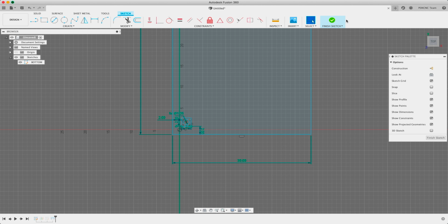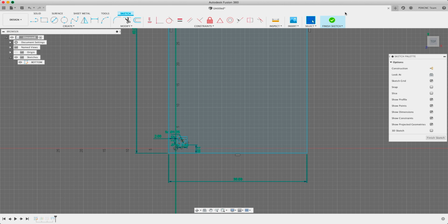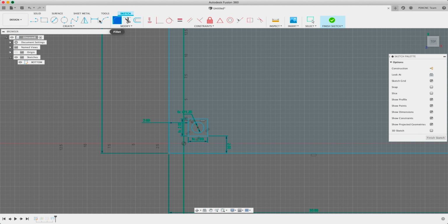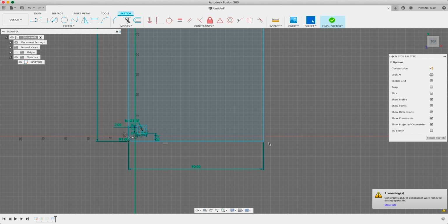So from there, actually, let's just go with a fillet on the corners here. Fillet, so I love a fillet. Fillet is up here in the sketch bar. That corner's a little big. I'm going to make it 1 inch. Enter. If you click one side and the other, it'll let you keep doing that. So you could type 1 inch.